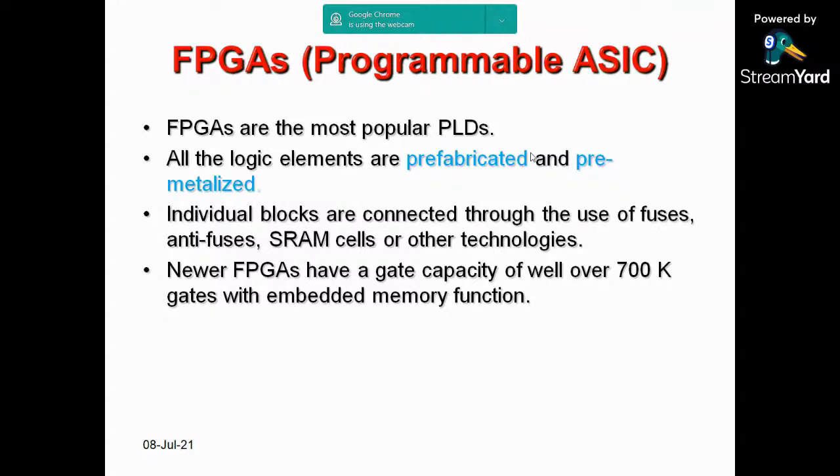Whereas with an FPGA, you can reprogram it, reconfigure it as many times as you want. So FPGAs are the most popular programmable logic devices. A basic FPGA architecture consists of lookup tables and SRAM memory cells, where you can program the cells. And when you program a cell, that particular cell will act as whatever you want.